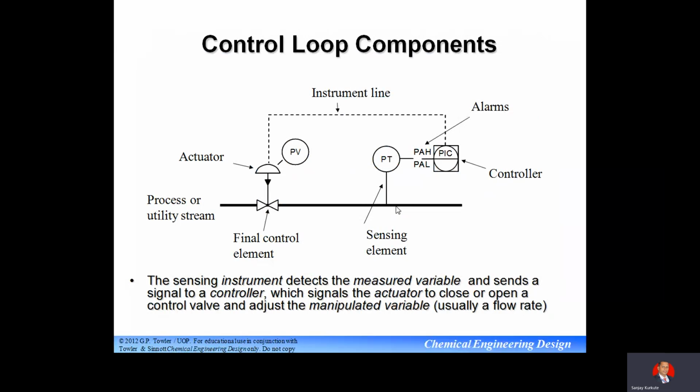Feed forward requires knowledge of system response, whereas feedback can be slow if process response time is long. So see the block diagram of the same system in case of feedback and feed forward.